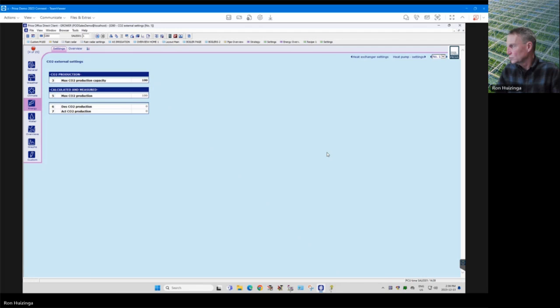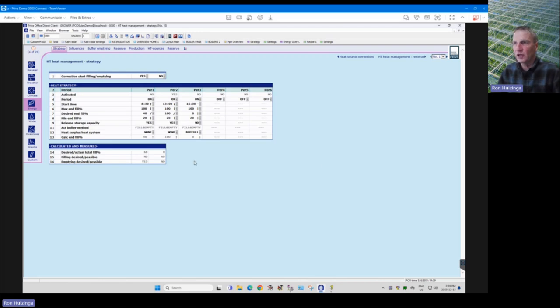Your minimum heat percentage you should have in your heat buffer tank for spring and fall. Yeah, that's the one I kind of started off with. For spring and fall, 20% is a good setting, and for summertime, like 10%. Wintertime is whatever you feel comfortable with. If you have some old boilers that sometimes break down, then maybe you may want to make it 50% in here.